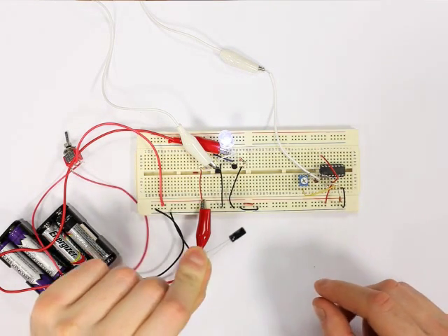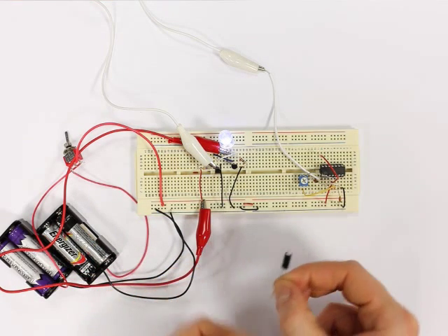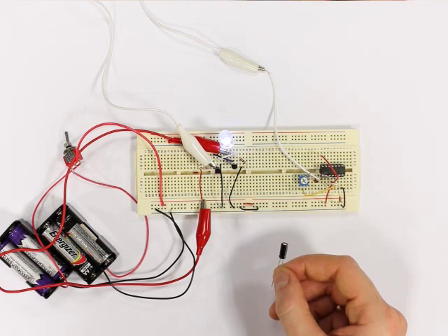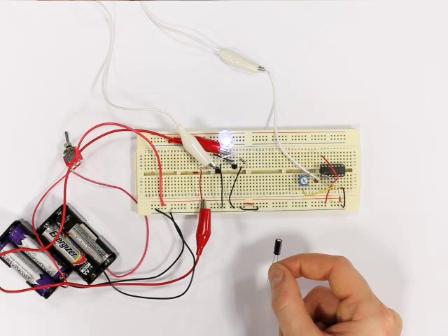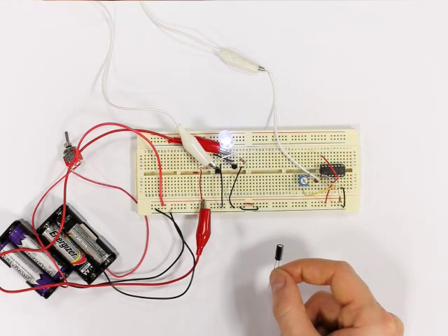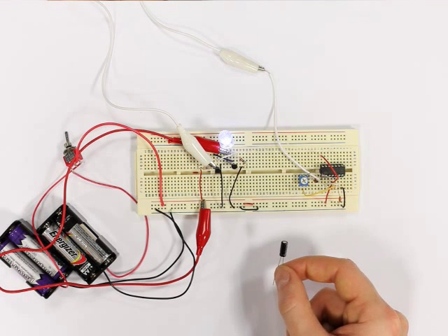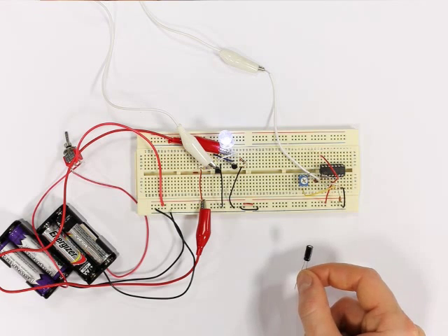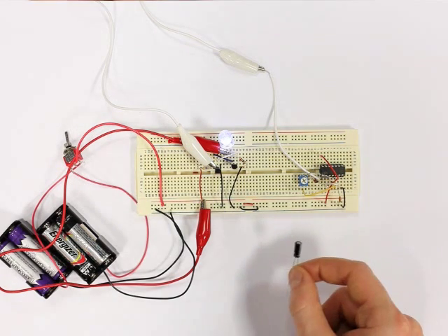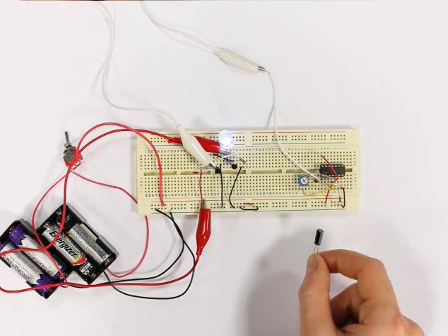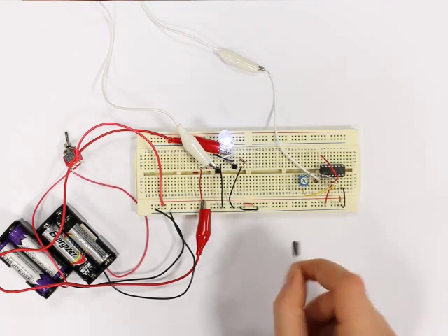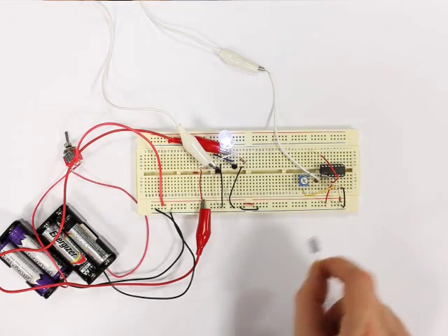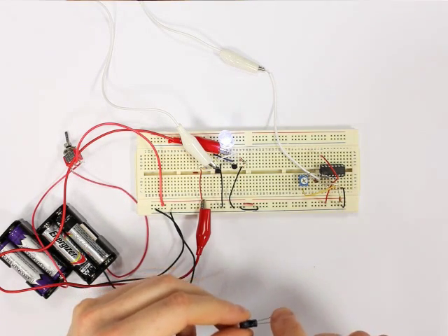I have here a 1 microfarad capacitor, which is 500 times larger than that one. And recall that if I place 2 capacitors in parallel, their capacitances add. So if I place this capacitor over the existing one, the frequency of the PWM should slow immensely. And if it's currently at 1 kilohertz, it should probably drop to around 2 hertz when I connect this cap, which is 500 times larger than the existing one.